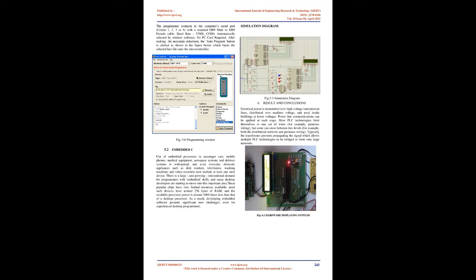At the left side of the debugger window, a table is displayed containing several key parameters about the simulated microcontroller, most notably the elapsed time, circled in the figure below. Just above that, there are several buttons that control code execution. The Run button will cause the program to run continuously until a breakpoint is reached, whereas the Step Into button will execute the next line of code and then pause. The current position in the program is indicated by a yellow arrow to the left of the code.